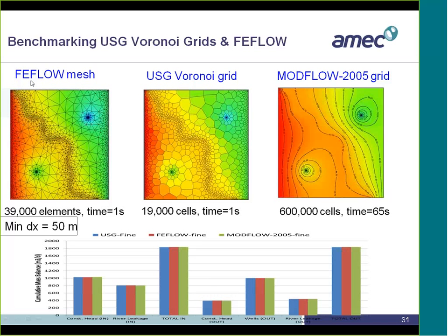Wayne will talk more about that, but the Voronoi grids are there and the MODFLOW 2005 grid, and those comparisons have been made. The FEFLOW fine grid also has been made, but I think they are doing some additional comparisons, and you can see pretty much you get the same results with all the grids.